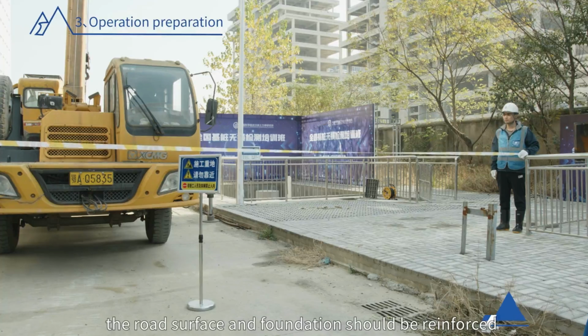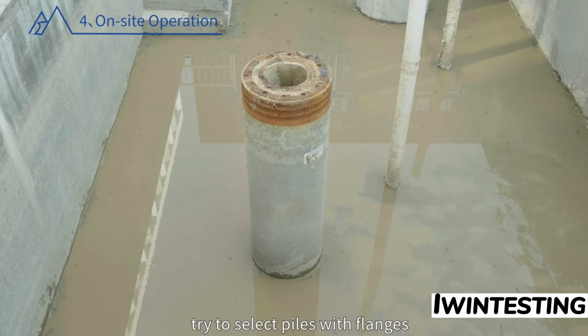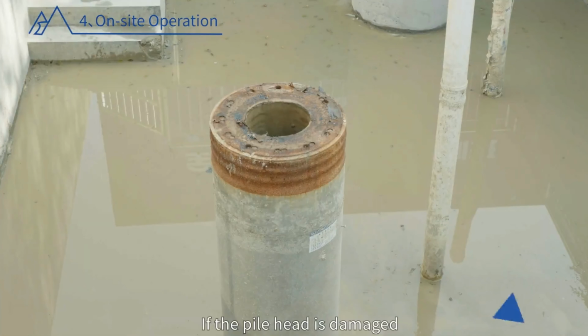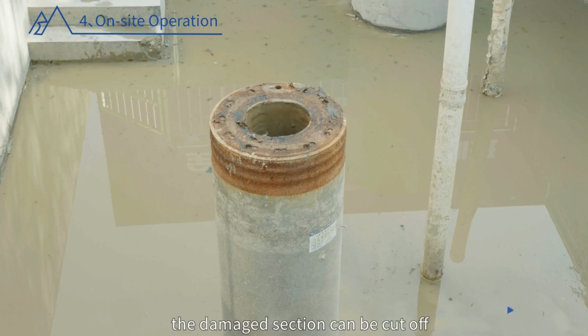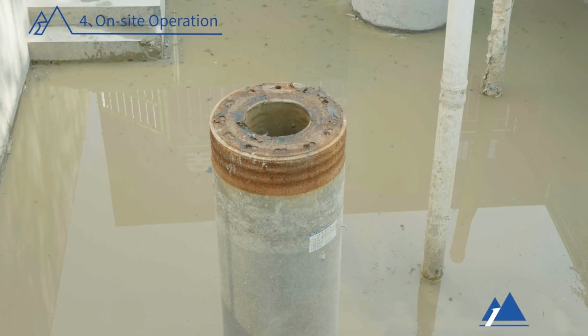4. On-site operation. 1. When testing pre-stressed concrete pipe piles, if conditions permit, try to select piles with flanges on the top of the piles for testing. If the pile head is damaged, the damaged section can be cut off, but make sure that the cutting surface is level and smooth.